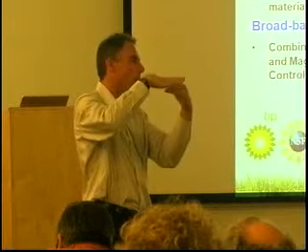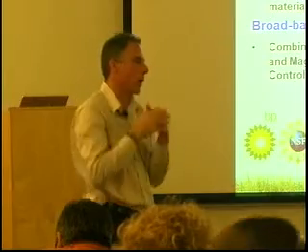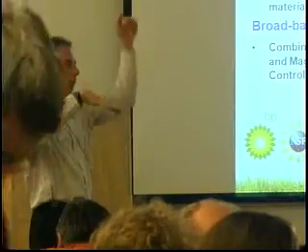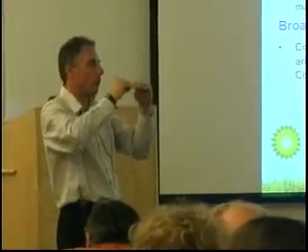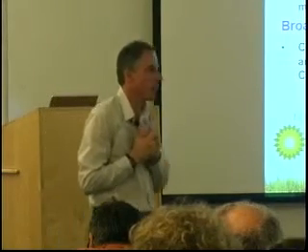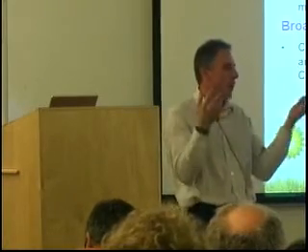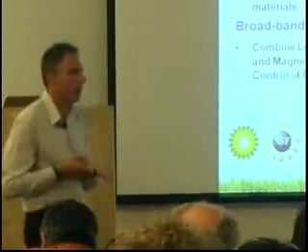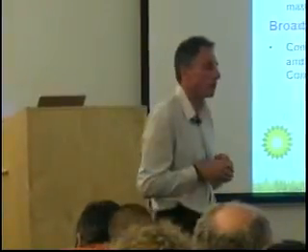So now you have optical intensity there, and if it's above the band gap, it generates photocarriers by ordinary absorption. But the main difference relative to light coming in as a plane wave is that the mode is extremely confined in a thin layer. The photocarrier excitation processes are just the same as they were. It's still silicon, with the same complex refractive index and the same absorption characteristics as a piece of silicon of some other shape would have.